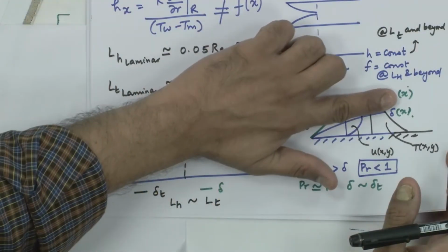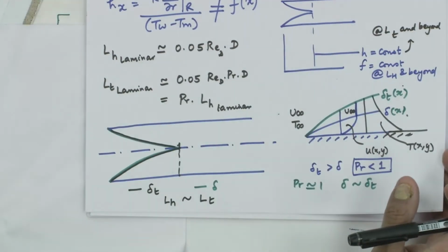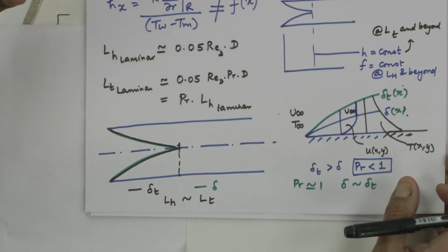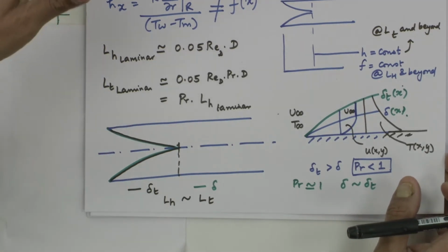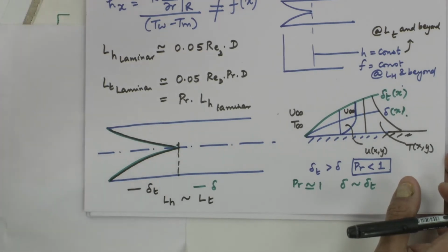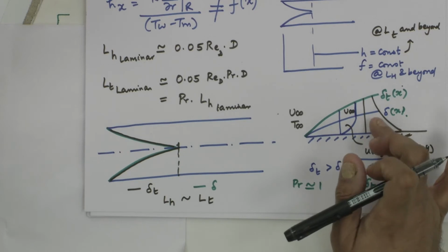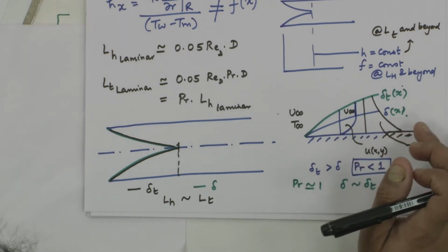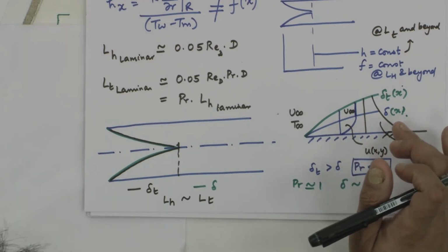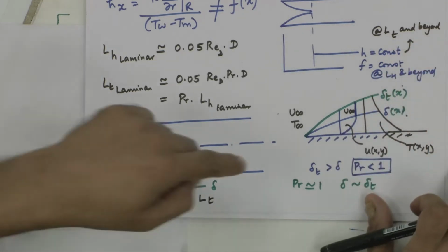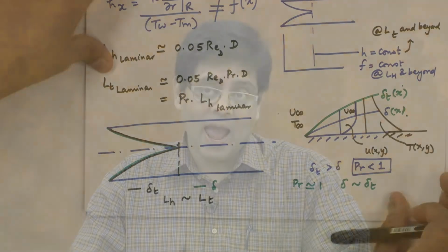When I looked at the Navier-Stokes equation beyond y equal to delta, I had to use u when I had the coupling rho Cp u dT by dx, the u was a constant u infinity instead of a variable u which was used here. So, the splitting of the region of the flow field into 3 parts, 0 to delta, delta to delta T and beyond, was made possible, and simplifications were possible because of this idea of Prandtl number.